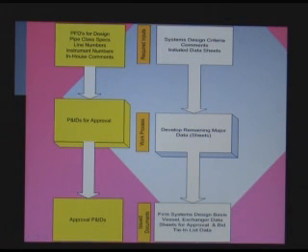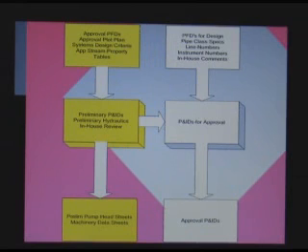Okay, so the next stage, when we have in-house review comments, I should have gone back one more slide here. We put those and other documents that are included, and we issue now officially the P&IDs. They should have everything included that we have ever known about the requirements of the client. We have put in all kinds of hydraulic information. All the lines have been sized with real numbers on them, real sizes. All the equipment is sized. Every basic type of information is on the P&ID.